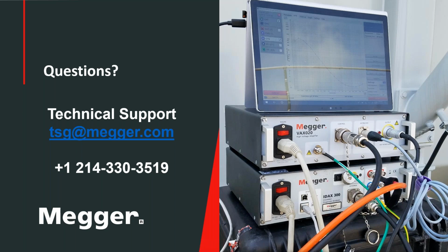VLF, you can do tan delta VLF, of course, but that typically for XLPE cable is a very low frequency, like 0.1 hertz, being applied to the insulation of the cable, but you're trying to go and stress the cable. So you're looking into the nominal voltage of that cable for the VLF testing.